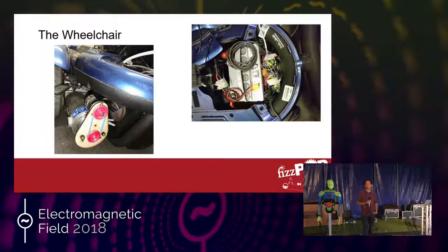Depending on the difference between the speeds of either motor, the robot will turn. The encoders feed back to the controller, which is an Arduino, fitted in the space between the battery and the front of the wheelchair. It feeds back the speed, and I just bought a pulse width modulation driver that takes a PWM signal from the Arduino and drives the motors.